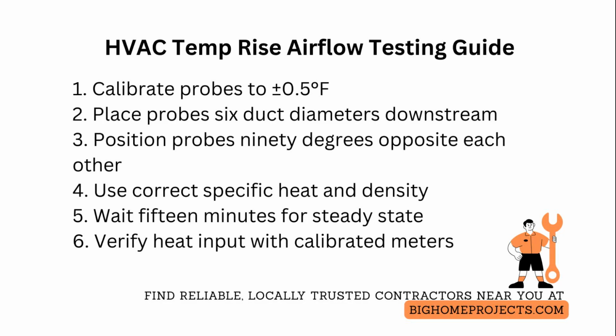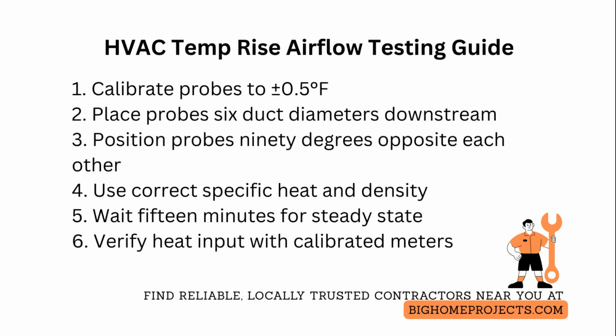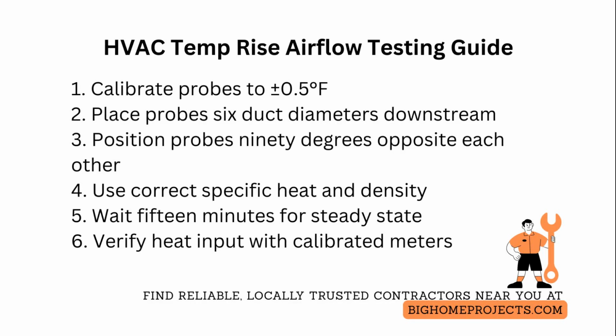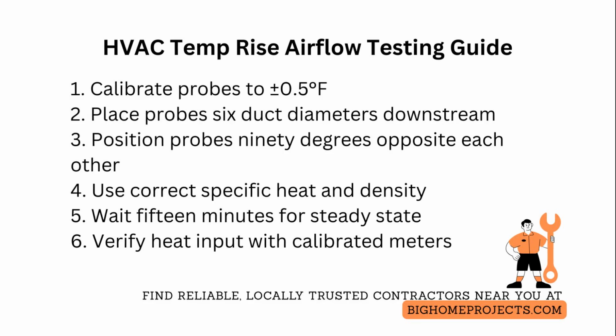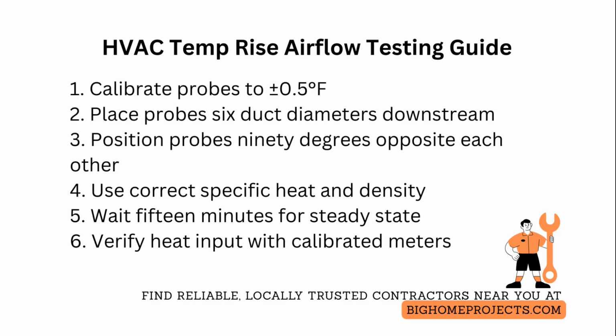Because assuming standard density creates measurable error, when heating, allow steady state for at least 15 minutes after the heat source stabilizes, monitoring that supply minus return temperature rise remains within plus or minus 0.2 degrees Fahrenheit over 3 consecutive 1-minute samples before taking final readings. Convert temperature rise to cubic feet per minute with the standard formula: CFM equals heat input in British thermal units per hour divided by 1,200 times the temperature rise in degrees Fahrenheit.